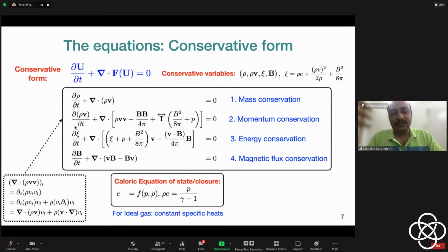So often what we do is we start off with a basic linear reconstruction, let's say. The flat reconstruction is not very helpful. The linear reconstruction is good up to second order accuracy. So we start off with the linear reconstruction and the most basic schemes that we have, and see whether our initial setup is running properly. After that, we gradually increase the accuracy levels of the other schemes. And if we do not find significant changes, we just go back to the previous scheme, because it is less accurate, but gains time. Okay, Vaibhav? Yes, sir. Thank you, sir.